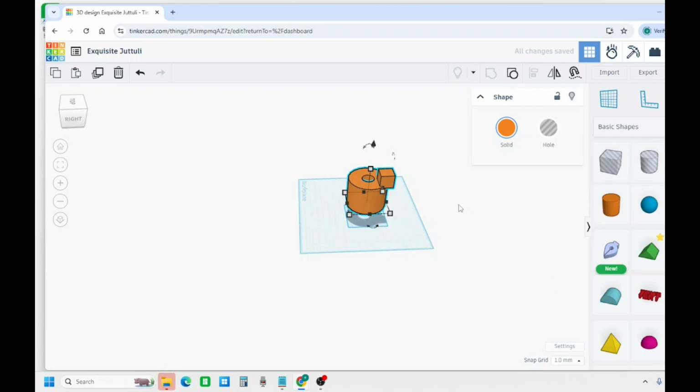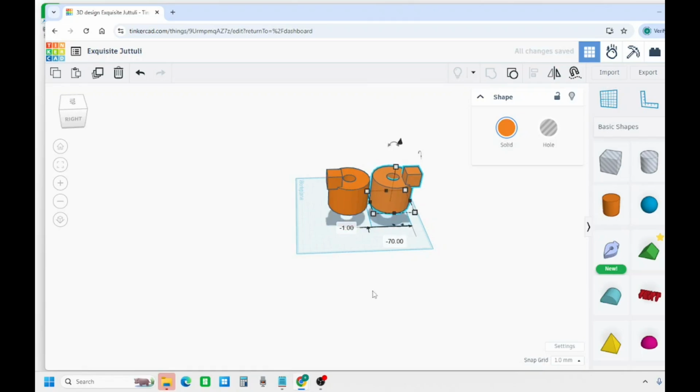And then let's see what else we got here. There's a lot you can do with Tinkercad. It's a very simple, easy to use, but useful program. So say you want to copy an exact mirror of this. You can go up here and hit mirror and use the arrows to align your new piece. You go duplicate, mirror, use your arrows, and now you have a perfect mirror of that piece.